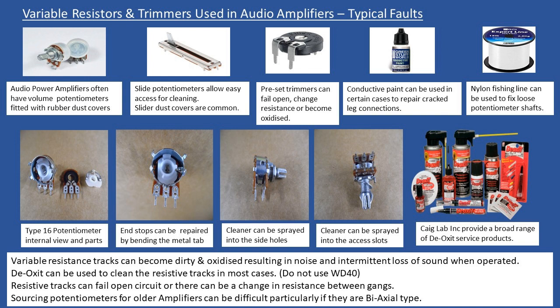If you're using it on switches, again, use specialized contact cleaner, but remember that it's not a long-term lubricant, right? So when I work, say, on encoders, or maybe I use this hack here with the nylon fishing line to fix the issue with a wobbly motor shaft or potentiometer shaft, what I'm using here is one of the products that you see displayed here within the DeoxIT series.